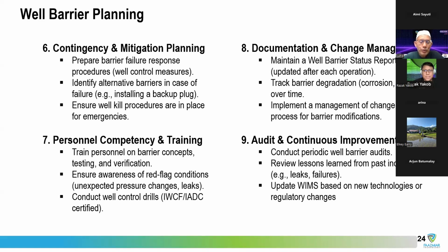But when you have well control in well intervention, you see it's different. For intervention, you have all your casing tested and intact, you have your tubing, and then you have a packer to isolate your pressure, and then you have open preparation, linking your pressure between your tubing, and of course the pressure in the reservoir is depleting, and sometimes you have some plugging. All those kinds of things will be different in controlling the producing well compared to the drilling well.